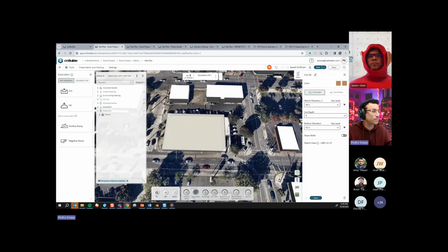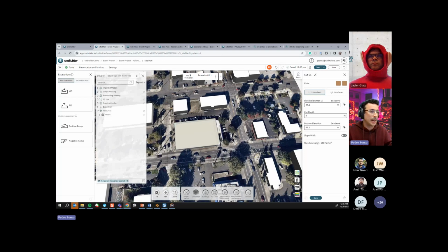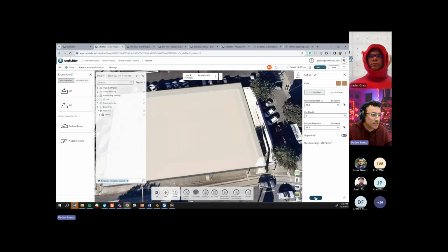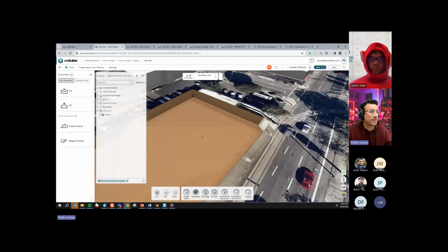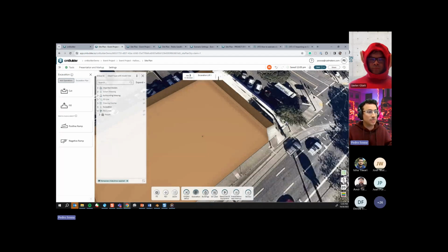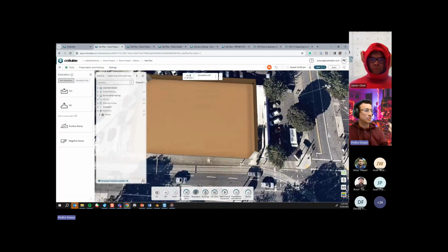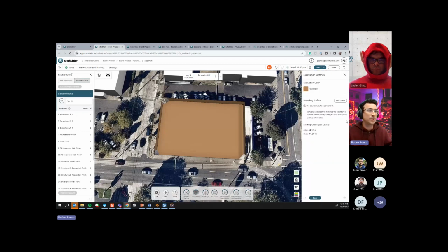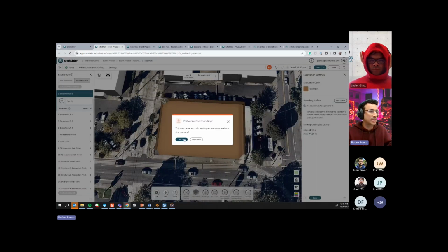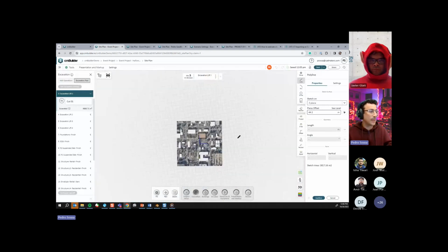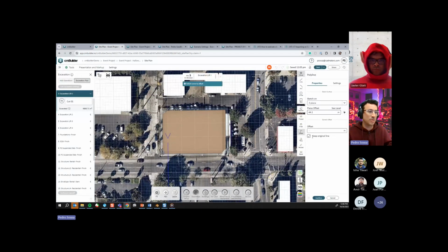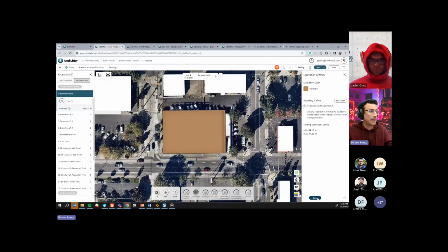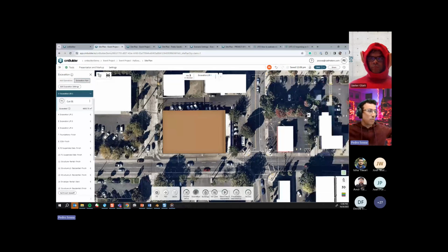Sorry, I just noticed that my excavation created these corners over here. You see that there's a little chamfer, and the reason is that our excavation boundary is too small for the cut that I just created. You can override that whenever this situation happens by going into your excavation settings, clicking on edit excavation sketch, and then increasing the size of your boundary. I'm going to create an offset and bring this excavation boundary a little bit bigger. The boundary is supposed to be way bigger than your excavation shape, so it will encompass everything.